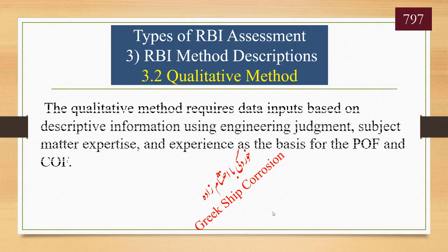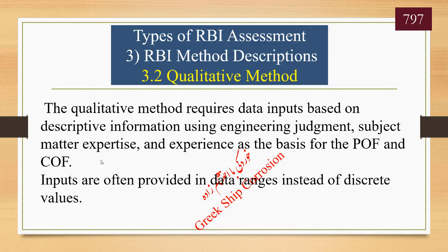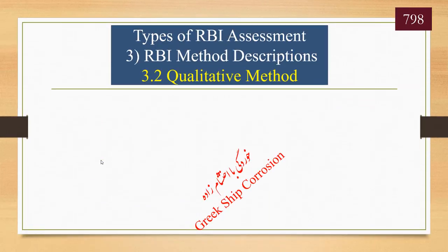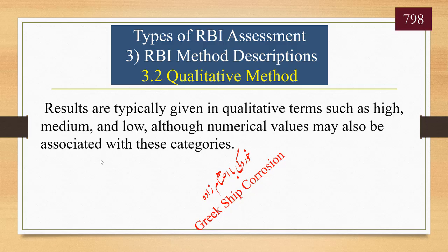3.2. Qualitative method. The qualitative method requires data inputs based on descriptive information using engineering judgment, subject matter expertise, and experience as the basis for the POF and COF. Inputs are often provided in data ranges instead of discrete values. Results are typically given in qualitative terms such as high, medium, and low, although numerical values may also be associated